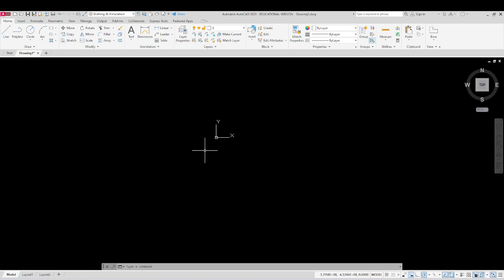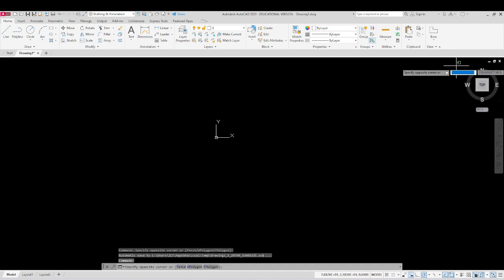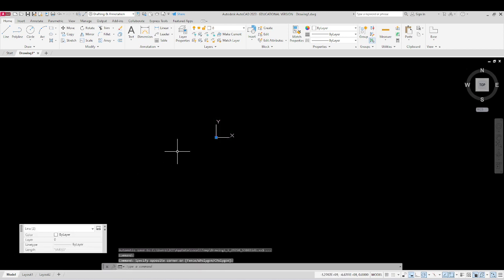So how to get it back, how to find the drawings you have drawn? For that, you can create a blue box, or you can create a green box like this. You can create it from the right top of the screen in this way, and try to select the whole screen. Whatever drawings you have drawn will get highlighted in blue like this. That means it will get selected. So wherever you find this blue grip, you have to go on zooming on that part.